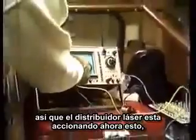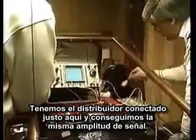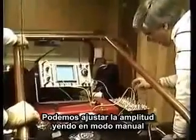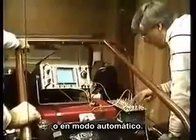Okay. So the laser distributor now is going to be triggering this. That's right. They're going to be triggering this so that those injectors are going to be firing right on dead center. When we hook up the distributor, all we have to do is hook this up right here, and we'll get the same response from the pulse width right here that we have. And see, I can adjust the pulse width by either going in a manual mode or in automatic mode.